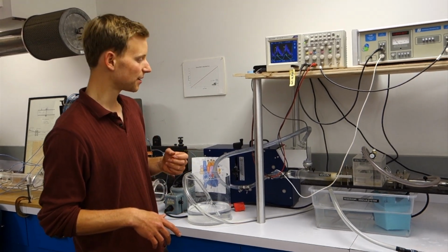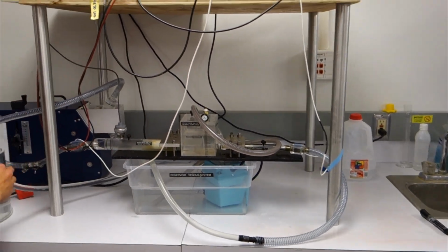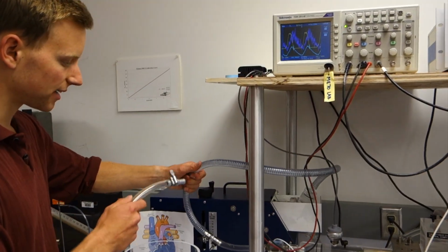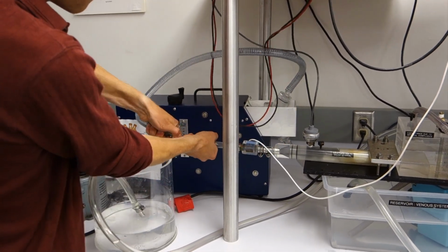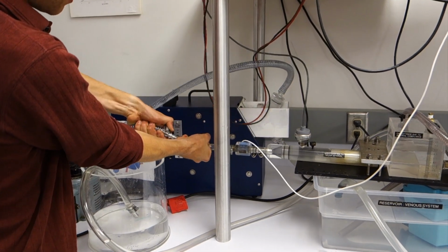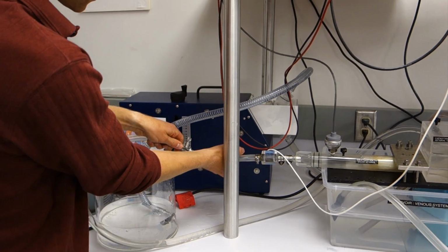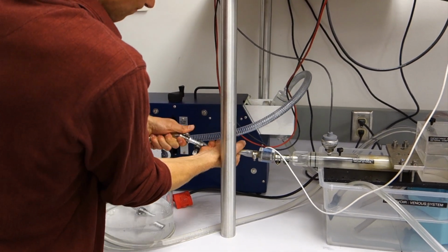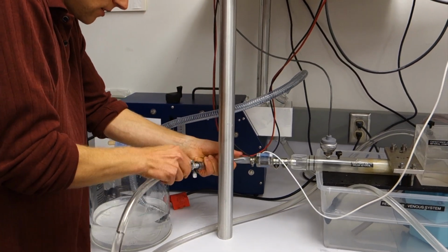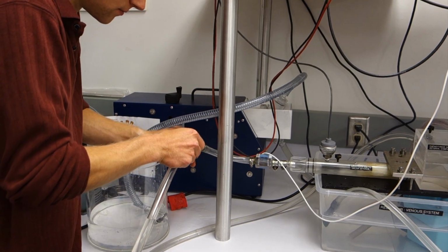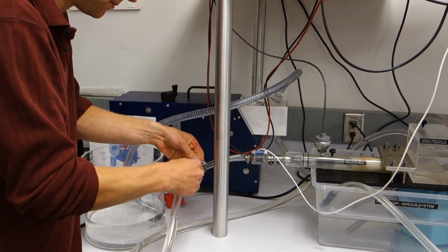So in order to use the steady state pump, I need to unhook my pulsatile pump, and I'll use this blue pump that's submerged under the water there, and that is my steady state pump. So I'm going to hook up that circuit and replace in exchange for my pulsatile pump, which requires undoing this thumb screw here. Being careful not to break the flow sensor Q1. There we go.